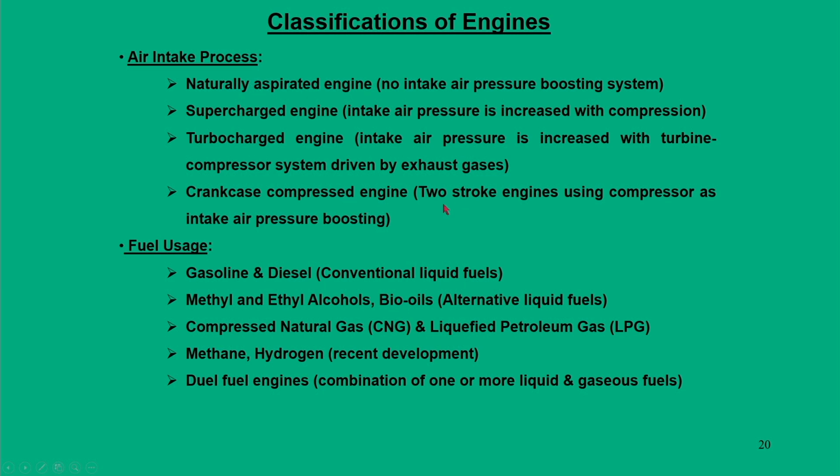But when we have a 2-stroke, there is the concept of crankcase compressed engines. These particular engines were used for 2-stroke cycles, in which they use compressors for intake air boosting. By default, in a 2-stroke engine cycle there was a compressor within the crankcase, so we say crankcase compressed engines. In fact, since there are no 2-stroke engines in the market, this concept is now obsolete.